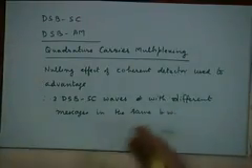The spectral occupancy of both the modulated signals would be in the same f_c plus or minus B hertz, right? So if you can do that, what would you do? You would increase your bandwidth efficiency by a factor of 2. In the same bandwidth you were transmitting only one message, now you are transmitting two messages.